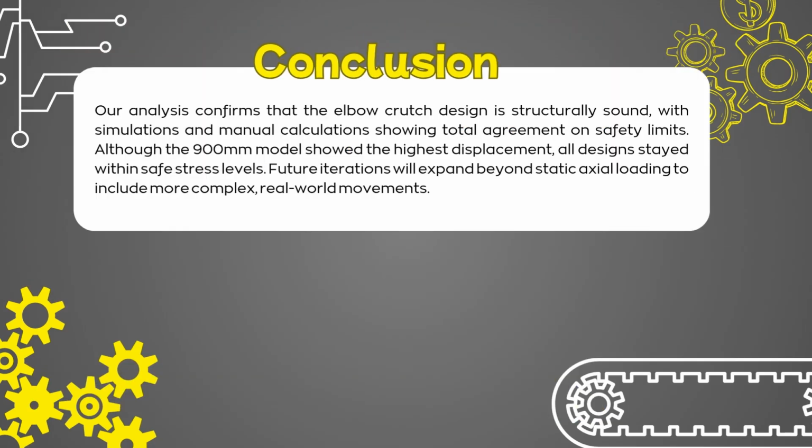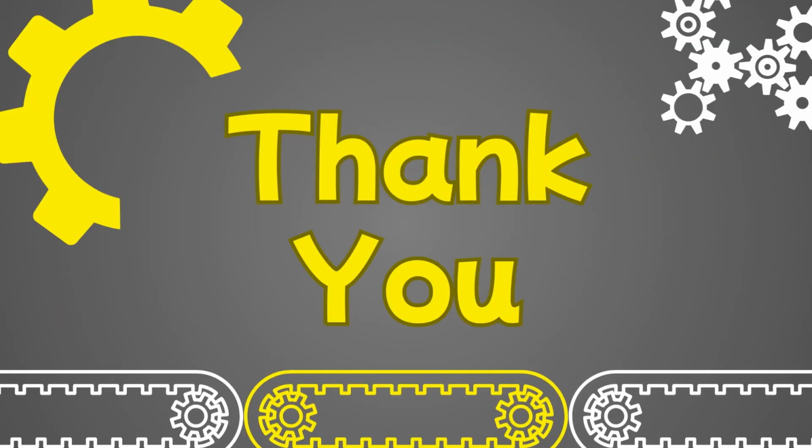So here comes our conclusion. Our analysis confirmed that the elbow crutch design is structurally sound, with simulation and manual calculation showing total agreement on safety limits. Although the 900mm model shows the highest displacement, all designs stay within safe stress levels. Future work will expand beyond static axial loading to include more complex real-world movement.